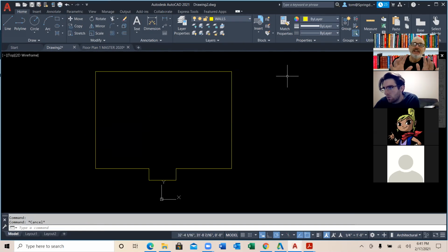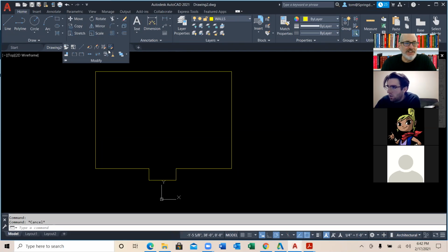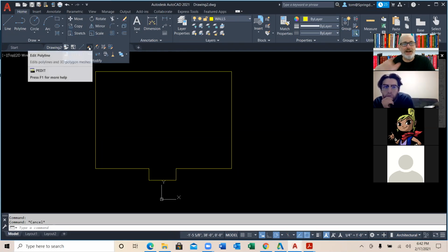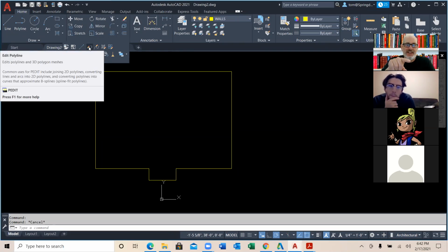And here's what I'm going to show you right now is worth the price of admission. I'm going to show you how to take lines and turn them into a polyline. It's not hard to do. The polyline command has a thing called the polyline edit command. Polyline edit is under Modify, and you can actually get it right here. It looks like the polyline command, which looks like a sideways J. That's the polyline command. We talked about that in the bracket discussion, but I think we did.